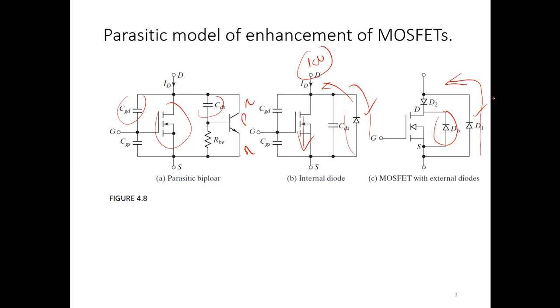But again, to prevent the current through the transistor from going in both directions, so that it is only one way, you put another diode D2 there, so that the transistor current goes from the drain to the source, and the freewheeling is done by the diode D1. This is the basic thing.